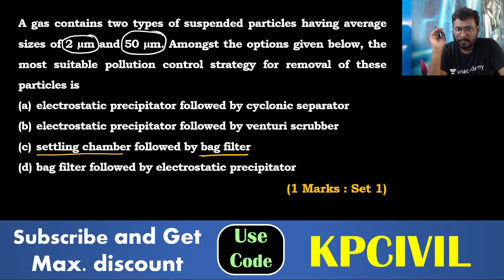What is D? Bag filter followed by electrostatic? No. We always go first electrostatic precipitation, then bag filter. And also 50 micron is there, without settling chamber we can't go for it. So the answer is: 50 micron particles are separated by settling chamber, followed by bag filter. Order of treatment is very important.